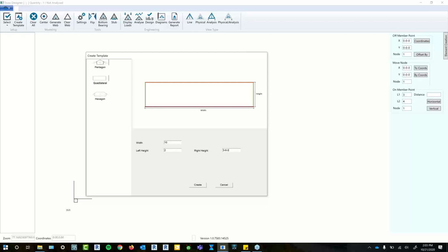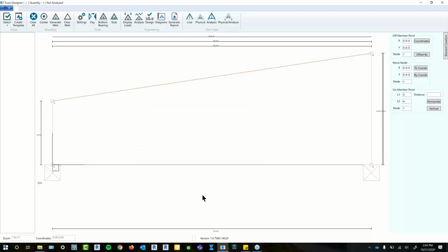So anyone, again, who's used the Truss software a little bit, the same kind of workflow still applies. So to input things in inches, you're just going to use the dashes, and I've got 3 feet, 6 inches, and then your last value is just to a 1/16 of an inch. So go ahead and hit create, and then you'll just get kind of the basic profile to start off.